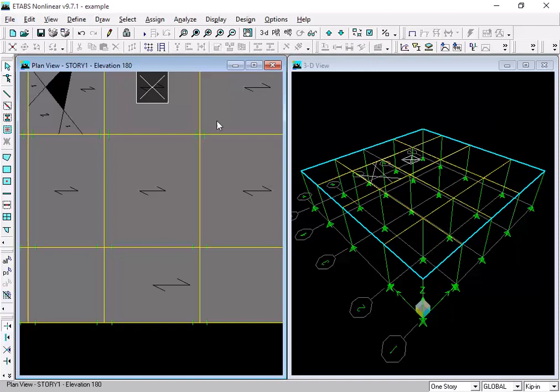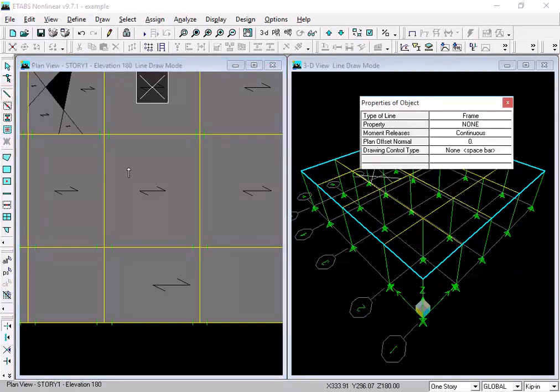So in AutoCAD, you can draw the outline of the atrium with the help of lines, and when you import the grids from AutoCAD, it will bring those lines, and you can create the opening. Or you cannot draw a curved line here. If you want to draw something curved, you have to take help of some straight lines.